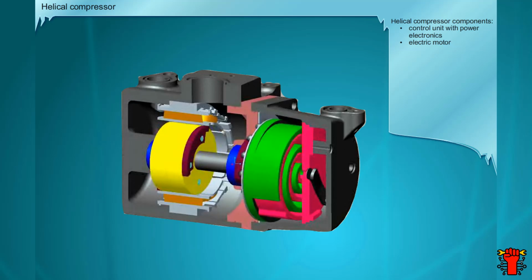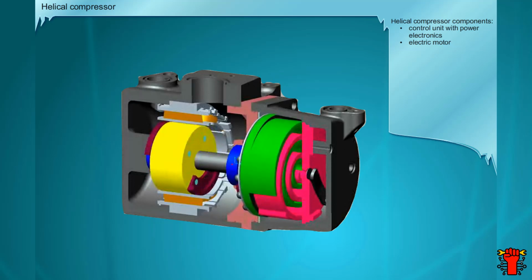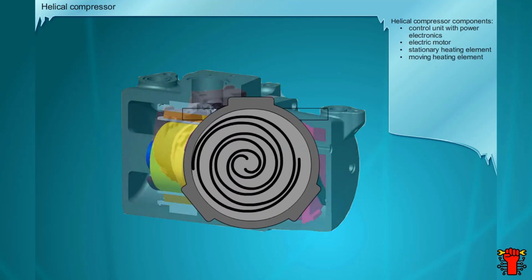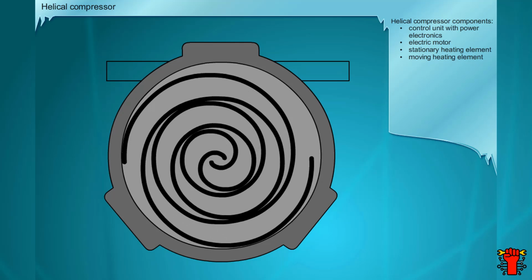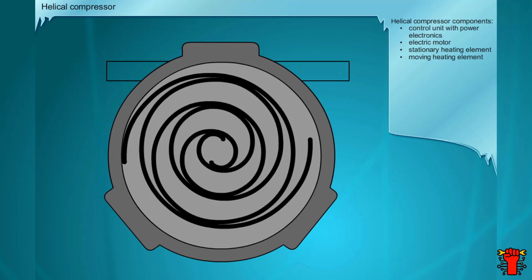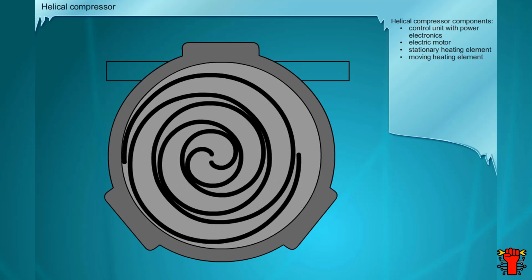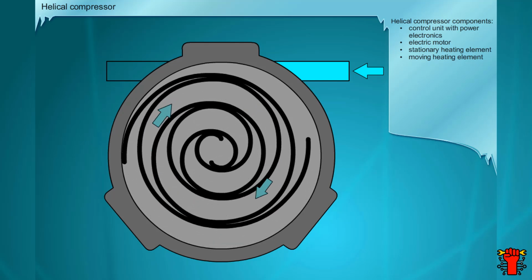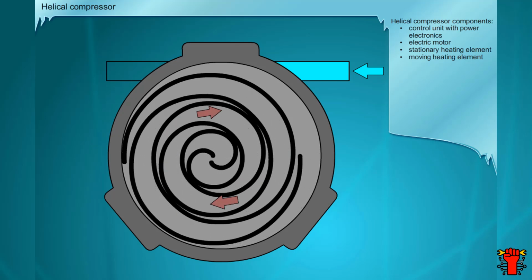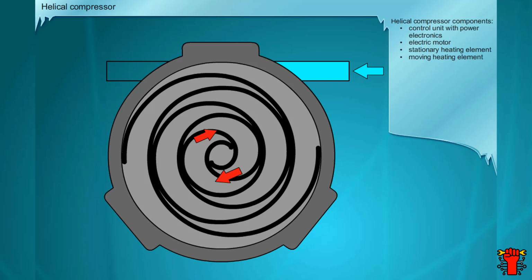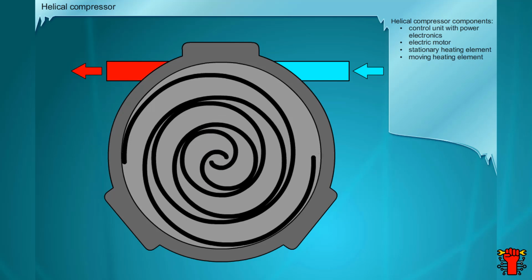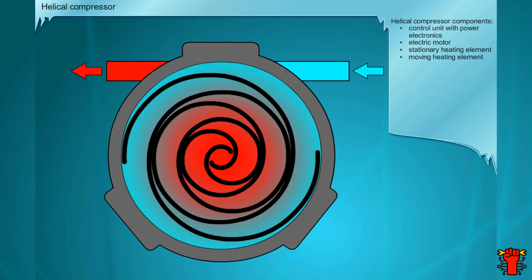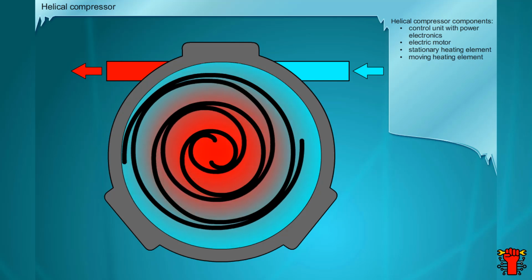Inside the compressor are two helices. One is stationary, while the other completes a circular motion. Through motion, a space of varying size is formed between the circling and stationary helices. Refrigerant is drawn in at the outer edge, conveyed inward and compressed, and then reaches the center of the helix. From there, it is compressed into the high-pressure section of the refrigerant circuit. Constantly drawing the refrigerant in and out results in a continuously subsiding process.